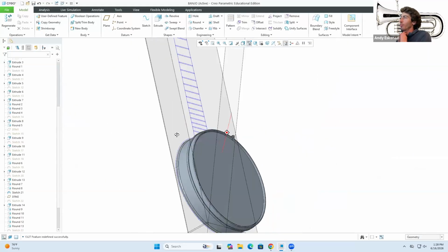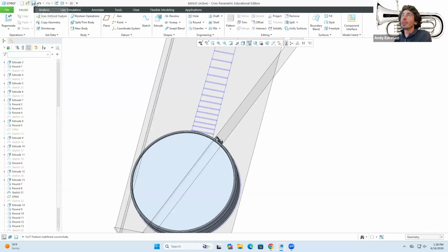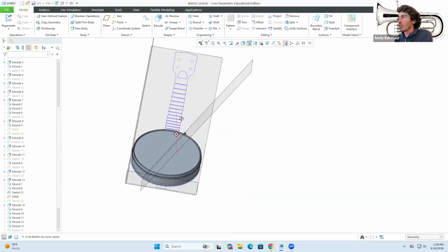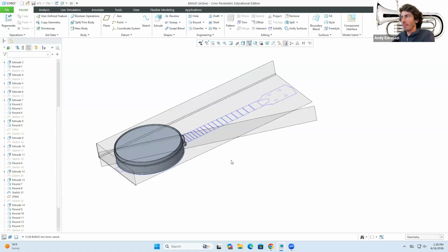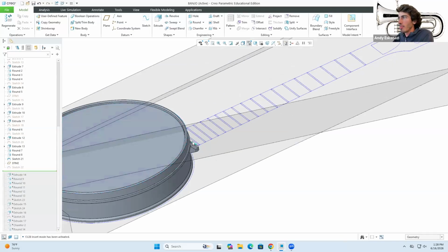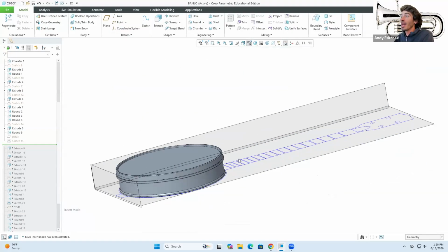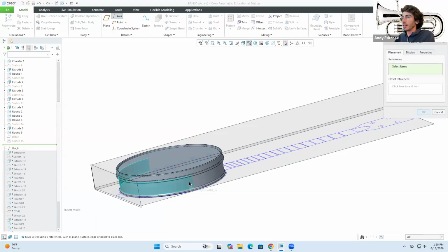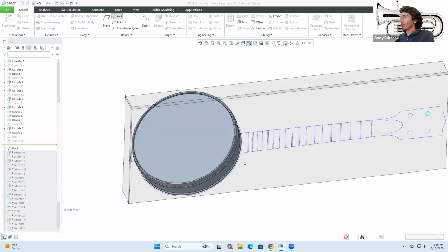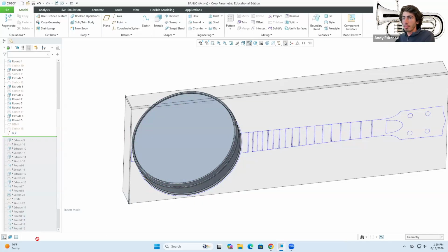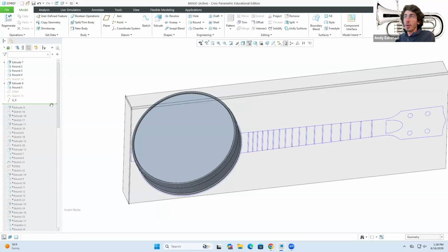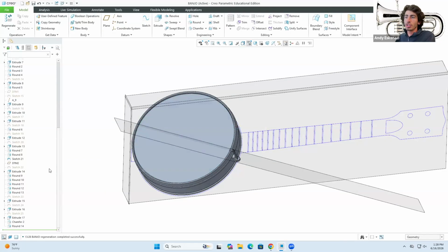Okay, there we go. So I was really just playing around, but again, PSA to save your file. So now that we are at this stage, let's actually do something cool with it. What I should have done from the very beginning is that I believe our very first piece is extrude 9. I'm gonna come back all the way there. I just created an axis, so I'm gonna create an axis. It's gonna go here. So now you see that goes in the middle. Perfect. So now I can come back in time, and everything that was created after the axis, that's what I'm gonna pattern. So it's actually something useful, right?